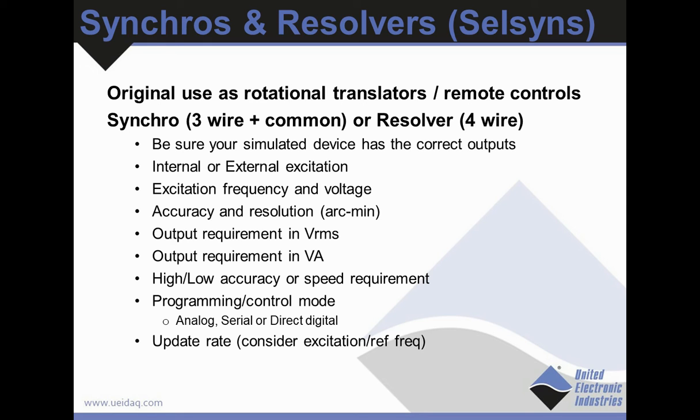A couple of things to note is that the synchro and resolver are very similar, but they're different. The synchro's 3-wire and a common resolver's 4-wire. So before you try and simulate a device, make sure your simulator has the correct outputs for what you're trying to drive. They can have internal or external excitation.